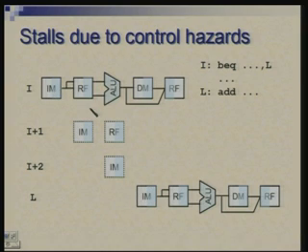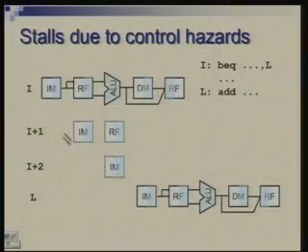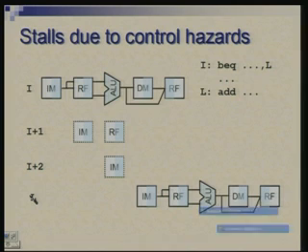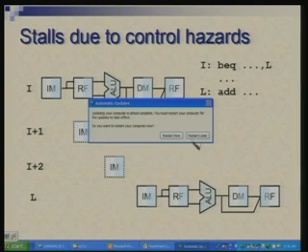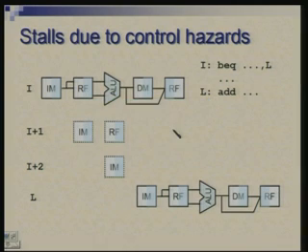the moment you notice a branch instruction, you freeze the pipeline, do not do anything, just allow that instruction to go up to a stage where the decision is known and then get the next instruction and proceed. So in the process you would have lost a few cycles, but that cannot be avoided. On the other hand, you might say that okay,